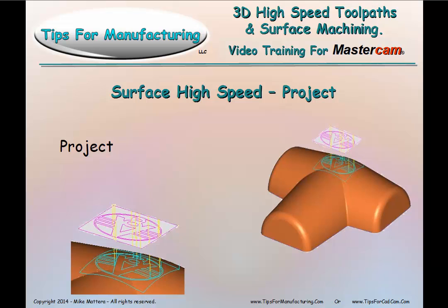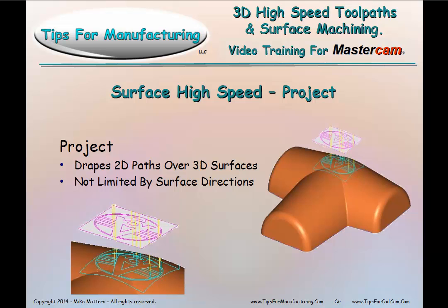Now this is project. So in this case, the example is they're projecting that V8 logo down onto the surface of the part and using that to create the toolpath. So this drapes 2D paths over 3D surfaces, and it's not limited by surface directions. You can engrave basic curves onto a surface.